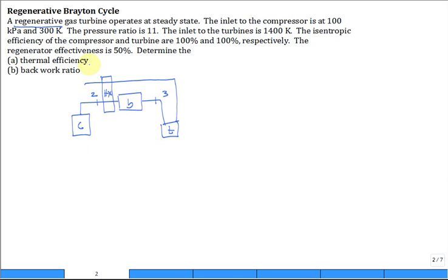And we still have to close the loop, so we bring it over and come down and then go into the compressor. But before we put it into the compressor, that regenerative heat exchanger doesn't cool it down enough, so you'll still have to have another heat exchanger, just like you did down here, to reject some heat to the ambient atmosphere. So this is Q out.